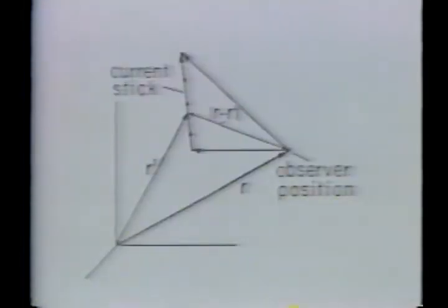Our square coils are composed of connected straight-line current segments, or current sticks. The Biot-Savart law is used to find the field at an arbitrary observer position r, associated with each current stick. Because the individual current sticks do not represent the solenoidal current density at its ends, the magnetic field derived is of physical significance only if used in conjunction with other current sticks that together form a continuous current distribution. Each of our square coils is composed of 4 connected current sticks.